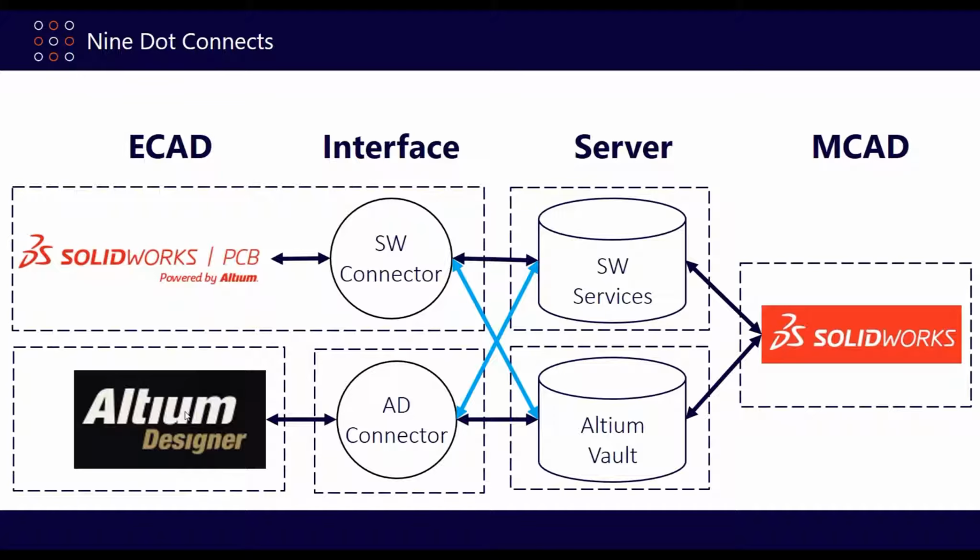If you're an Altium user, and that's what we're going to demonstrate here today, you also need a way of connecting into SolidWorks to take advantage of this. So you have an extension called the Altium Designer Connector. This is a paid-for connector. If you go into the updates and extensions that Altium Designer has, you'll see it there, but once you download it, it's going to prompt you for a license. So that's something that would need to be purchased.